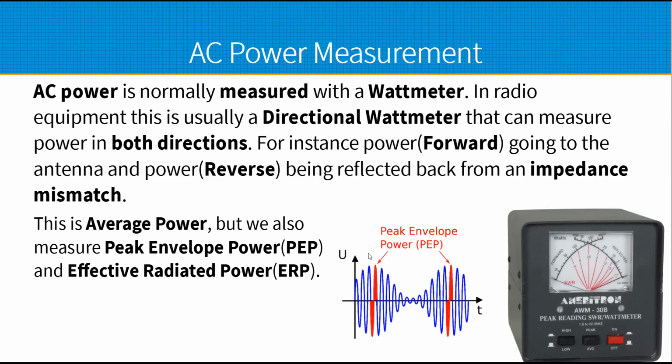So they will be the same. That's a test question about the difference in the two. I think the way they do the question is they give you an unmodulated carrier wave and want to know what the peak envelope power is. It's the same.